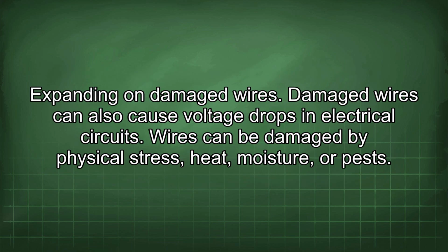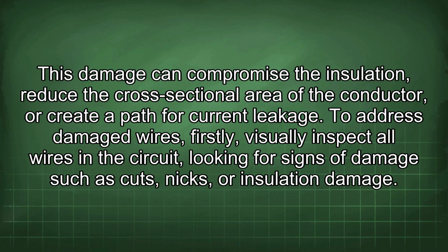Expanding on damaged wires. Damaged wires can also cause voltage drops in electrical circuits. Wires can be damaged by physical stress, heat, moisture, or pests. This damage can compromise the insulation, reduce the cross-sectional area of the conductor, or create a path for current leakage.